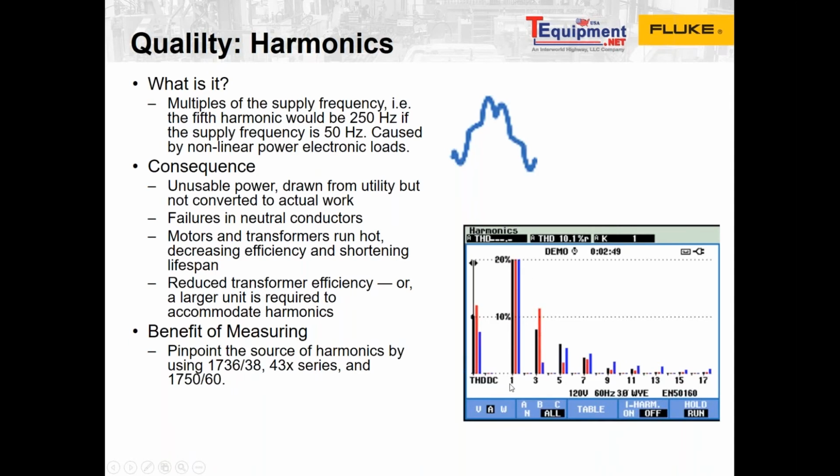You can see here that the third harmonic, which I think this was taken for 60 hertz. So at 180 hertz, you're experiencing some kind of third harmonic. And then, sorry, at 5 times 60, 300, you're experiencing some kind of harmonic here. I can't do math. So the system isn't exactly clean, but the nice thing about this Fluke tool is that it has the standard in it, and you don't have to figure out what your harmonic limit should be. It just figures it out for you, and it flags it for you in a different screen. This one just tells you your overall harmonic distortion.